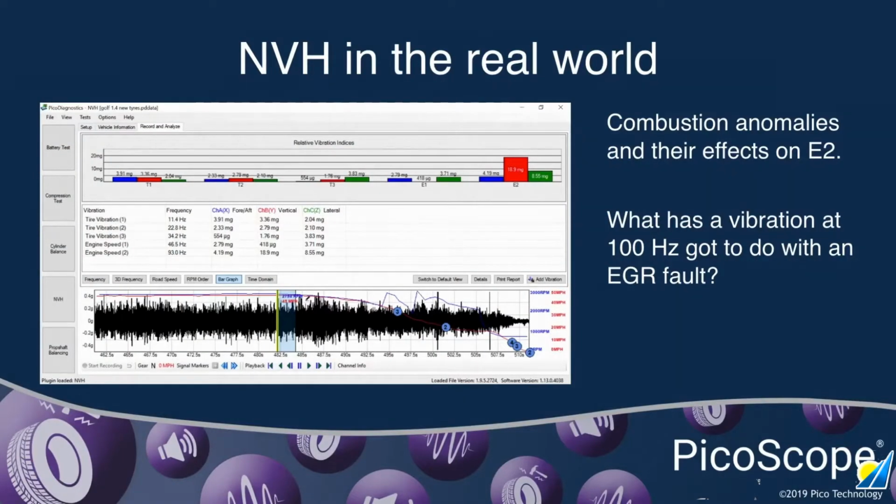Yes, and also if there was a combustion related anomaly, then my take on that would be that some of that energy would then be transferred to E1, the crankshaft, and there wasn't. The actual value of the crankshaft vibration was almost nil, as you can see from the graph. So that's what kept me focused on the fact that it was something related to a component at twice the frequency of the crankshaft. And of course that then led me to the ancillary pulleys on the front end of the engine. And just in time by the sound of it, Frank.